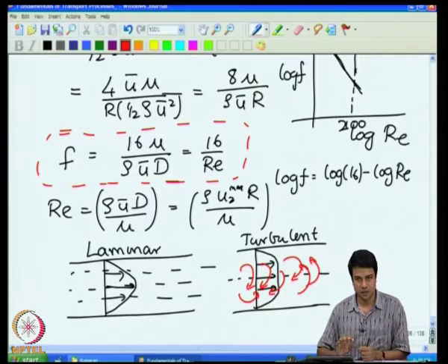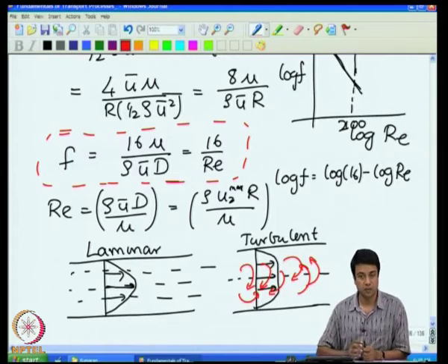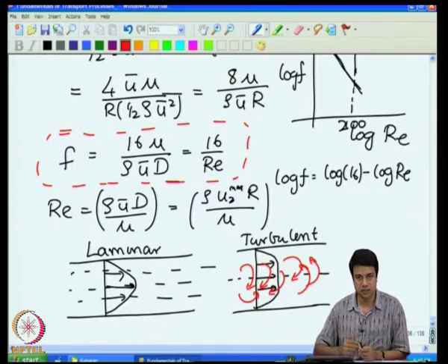They are basically parcels of fluid undergoing correlated motion within the flow, and these eddies transport momentum in a far more efficient manner than the molecular diffusion, because you actually have diffusion due to the actual transport of fluid across fluid velocity fluctuations themselves. In the case of laminar flow, it is due to molecular fluctuations. In the case of turbulent flow, it is due to macroscopic fluid velocity fluctuations in these eddies which develop spontaneously.